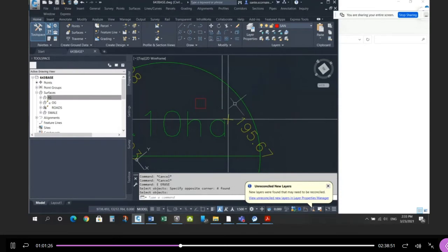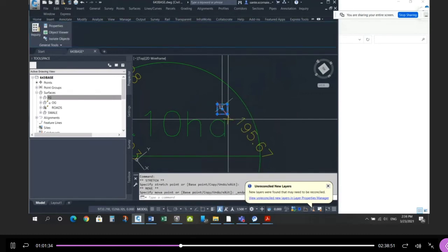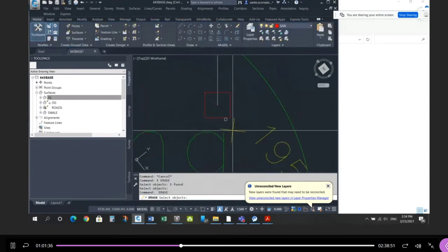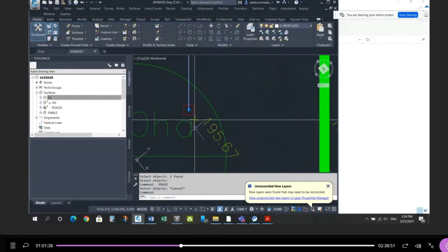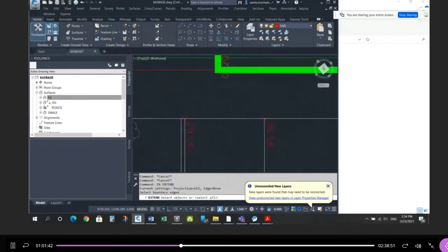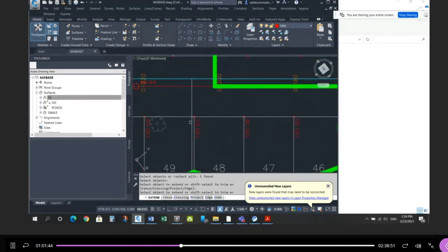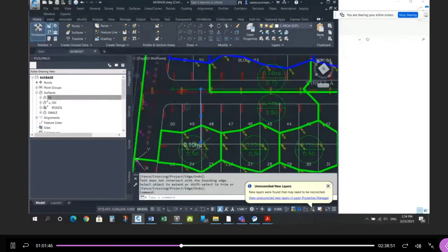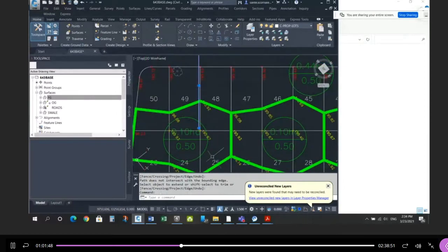It's schematic. Do you want the catch basin to be parallel to the side yard? I'm going to draw a line from here to here so I can find the center and move it to here, and there's your rear lot catch basin. And there's the pipe that takes you to the street, so I'm going to extend that to the sewer on the street. And that's the pipe that's going to be designed by this area.